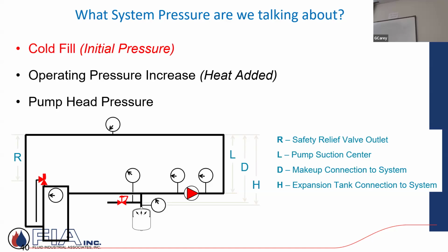So you look at this very simple drawing here. We've got a boiler, what's missing but should be an air separating device, and then our expansion tank connected. We've got a distribution pump feeding a piping system back to the boiler. Very simple. And they're getting very detailed because a lot of times when you talk about these things, you'll say, hey, the fill valve, the relief valve, the expansion tank, they're right there. They're all in the same plane. We're not doing this. But here they're getting a little specific.